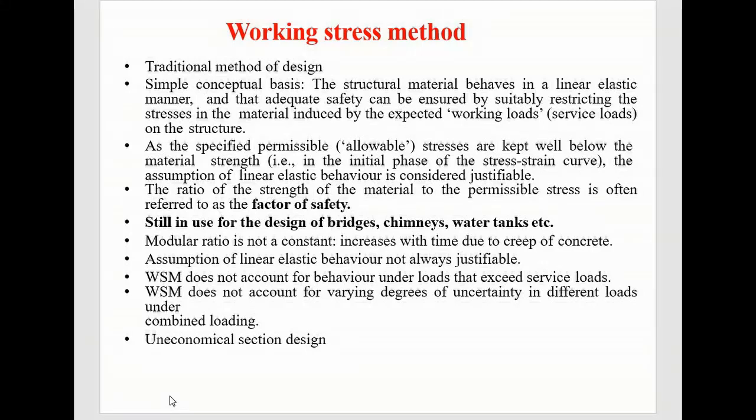This method will give nominal size and reinforcement, so it is economical. But this method will not take proper care of the serviceability criteria. That is, in this method both deflection and cracks were large. So due to this drawback, this method was not carried forward. And to overcome this, one more method evolved, that is nothing but the limit state method.